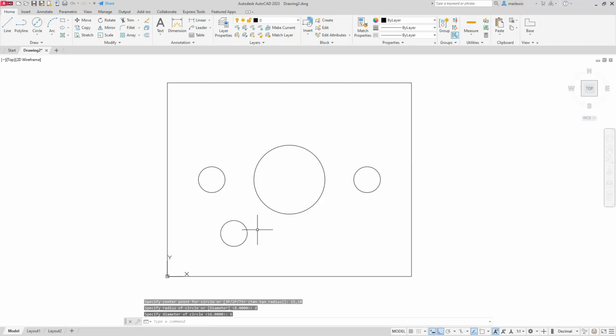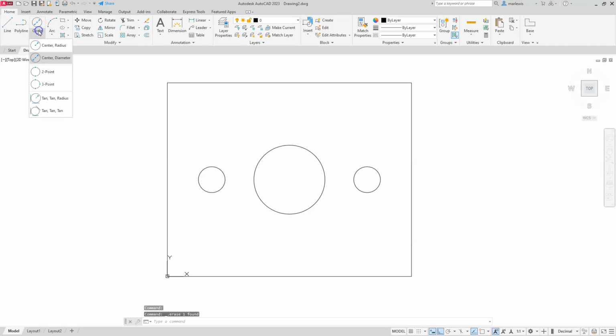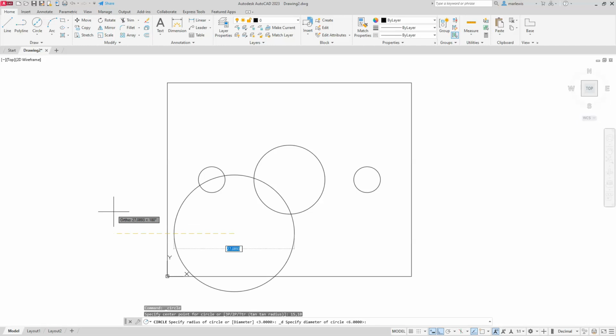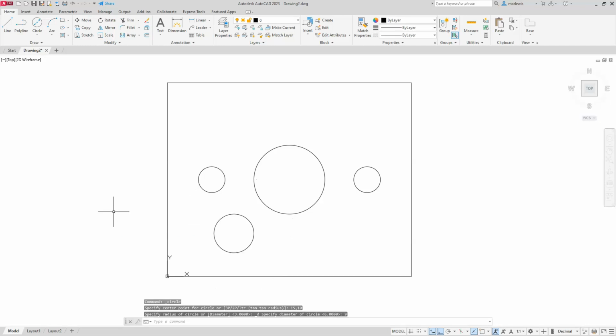And I'm just going to hit the enter button again. Oh, I am so sorry. That diameter is 9. So I do have to go ahead and erase this one. So I'm going to delete this one. And I'll go back and use my circle center diameter. And I'll type that in again. So that's going to be 15, comma, 10, enter. And it has a diameter, so D, enter, 9. Okay. Now I'll hit the enter button.